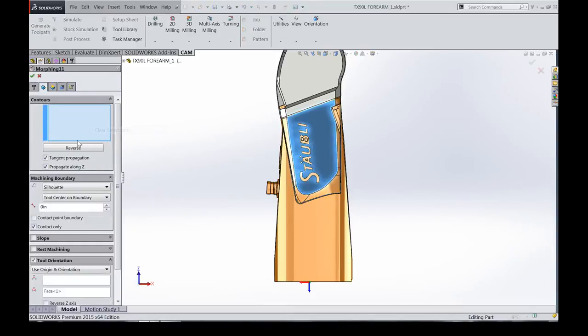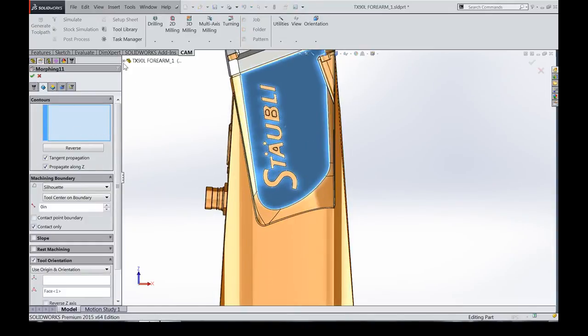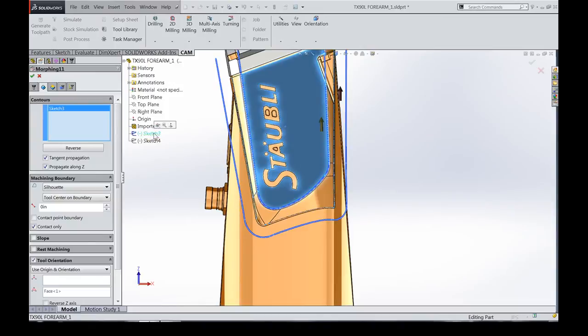Let's get rid of this crap. Let's grab our sketch. Grab this one first. It's important, especially when you're selecting a sketch, to make sure that they're both still going the same direction. It's not uncommon that they'll wind up opposite from each other. And if it does that, you usually need to break your sketch up into two pieces so that you can select each guide curve itself and be able to reverse it. If you reverse it, it reverses both.